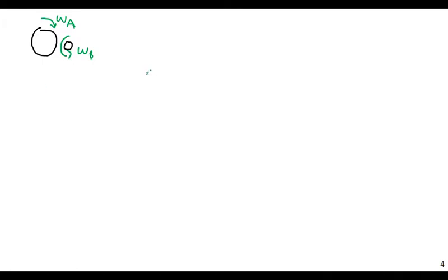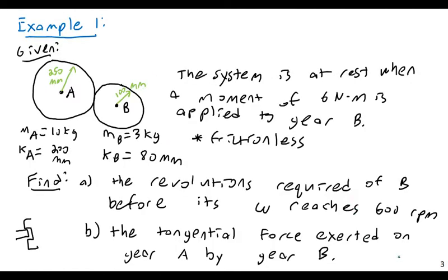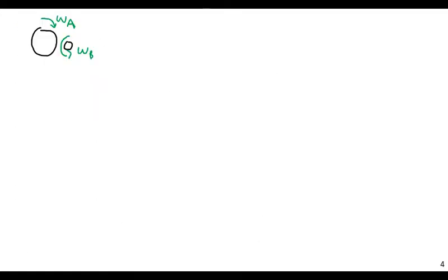It's just like if I connected one wheel within another wheel. You know, I have say a drum and a spindle inside, or a drum connected to a big wheel or something like that, like we've seen previously. In this type of system, they don't have the same tangential velocity, but both of the joined systems do have the same angular velocity. So spinning objects, depending on how they're connected, can either have the same angular velocity, the same tangential velocity, or neither or both. Okay, so anyway, whenever you have two things joined together at a shared outer surface, they're going to have the same tangential velocity.